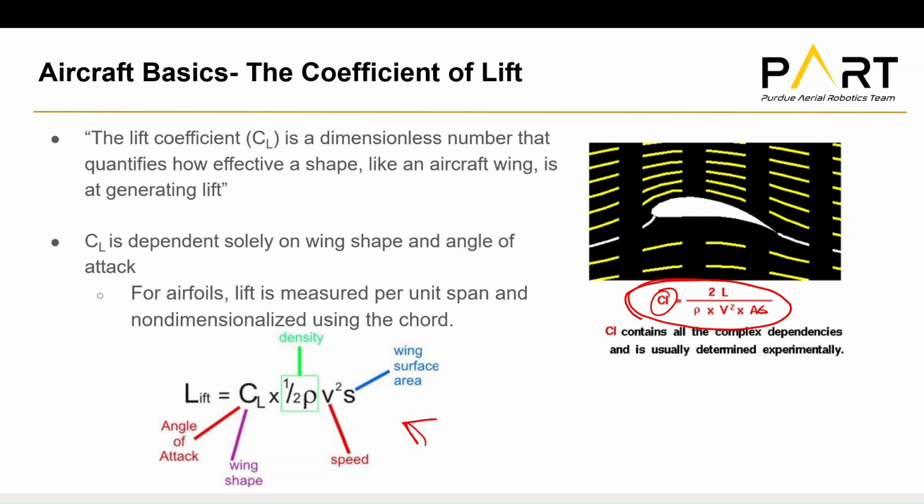Then you take the airfoil, you put it onto your plane, and because the airfoil's already been found dimensionlessly to have a CL in the wind tunnel of X, now we can put that on our plane and say, here's the total lift of our plane based on the CL of the airfoil, and then the flight speed, wing area, and density of the airflow for our actual plane.